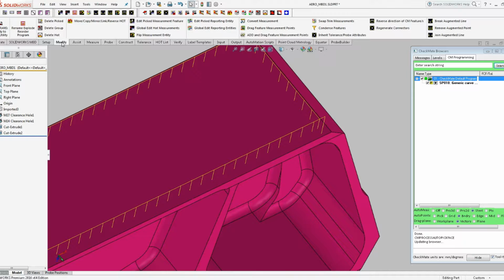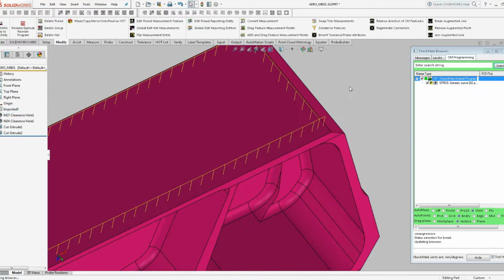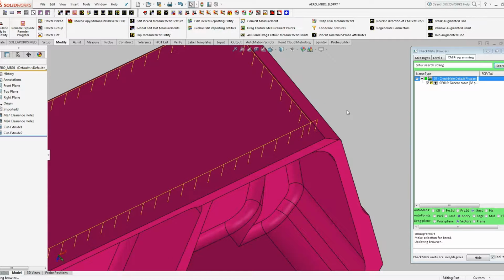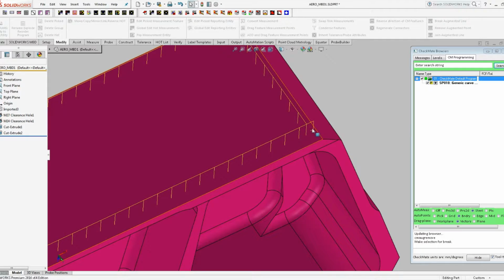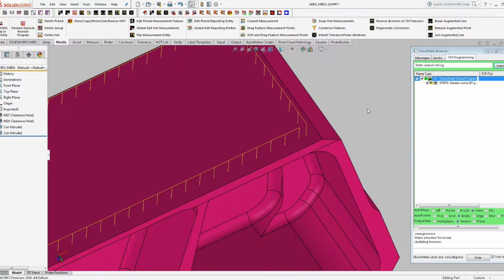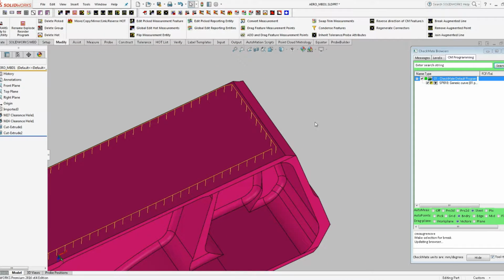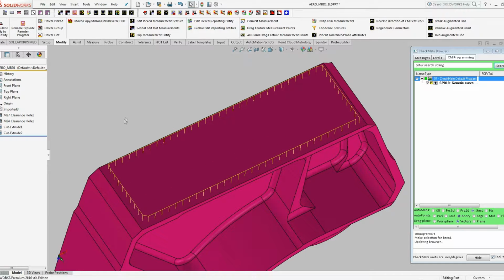So if we go to our modify ribbon, and over on the right hand side we can say remove augmented point, and let's just click on this one that doesn't really belong there. So we'll click on that, and how are we looking here? Let's do one more. Let's get rid of that other one. It's a little close to the edge there, and we'll pick it. And there we go. So we've got some nice measurements going around the boundary of this face.